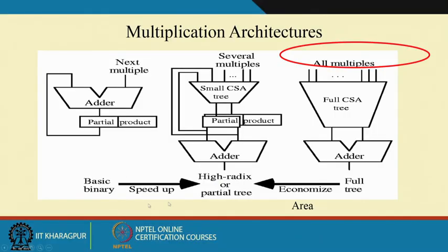There also we are doing this reduction in the depth of the adder chain operation, using this binary tree. So, in today's class we will see those tree multiplications, or how we can reduce the number of delays or the number of full adders, in what aspects I can basically do the reduction. Let us start with this tree multiplication.